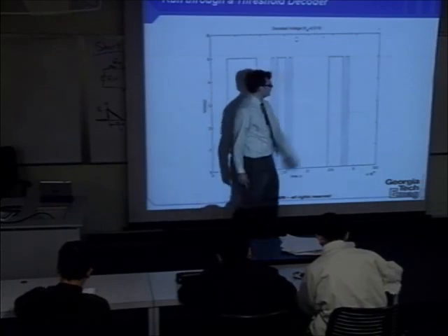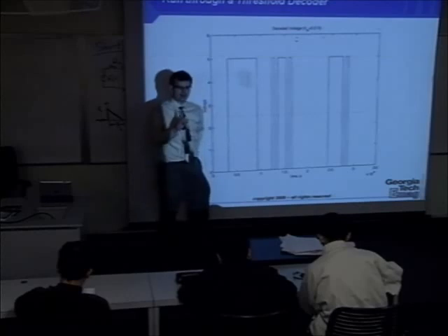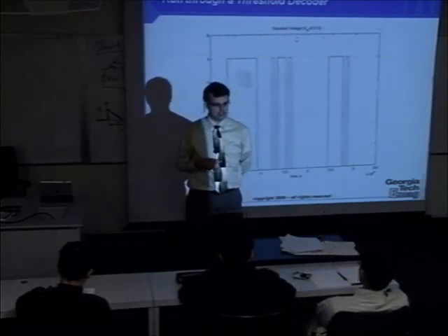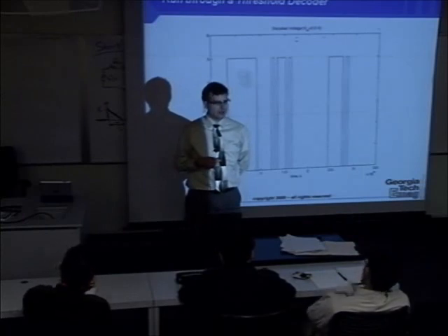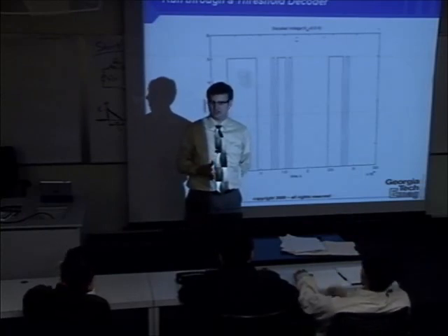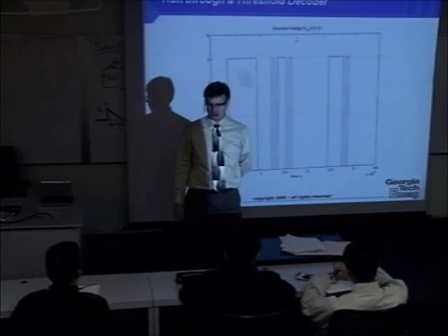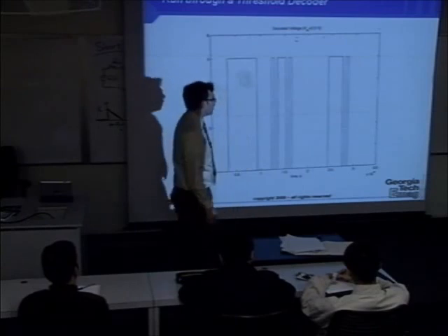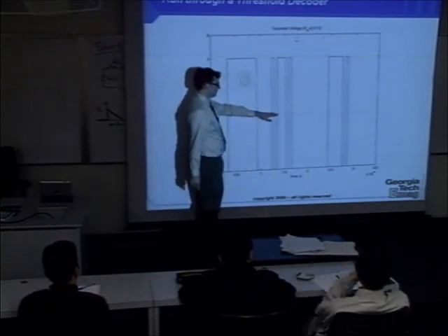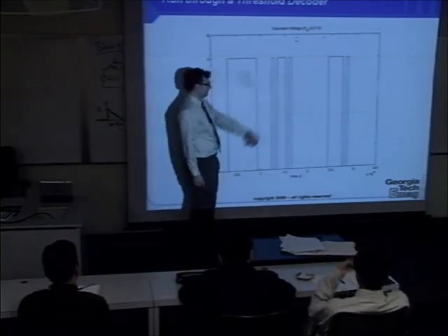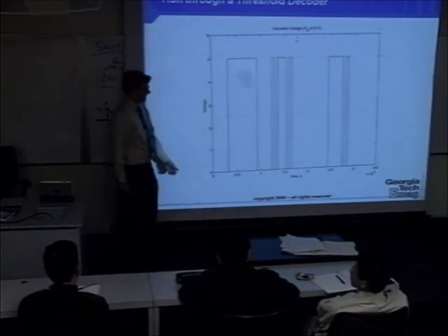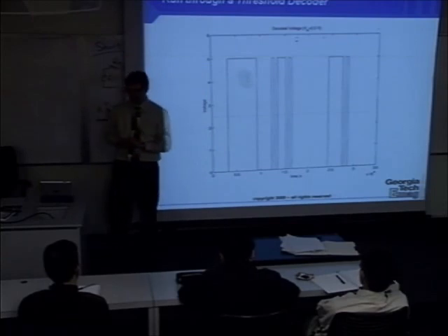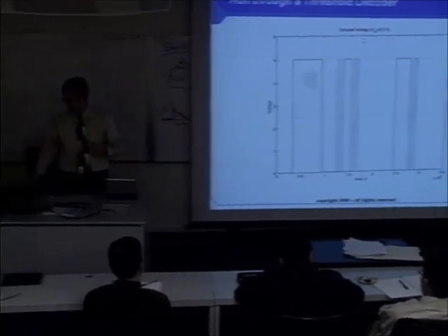Same with over here. So just running this signal through a straight up threshold detector does not reconstruct the perfect digital sequence we sent. What I would probably do is run this through a low pass filter and then do a threshold operation. Low pass filter to get rid of some of the ringing, and then hopefully that'll get rid of some of that intersymbol interference, and it won't push my total signal below the threshold when I have a 1, or above the threshold when I have a 0. Now, that's a simple way to deal with the problem.